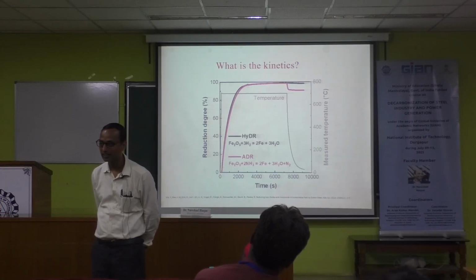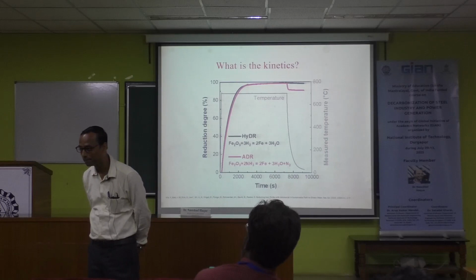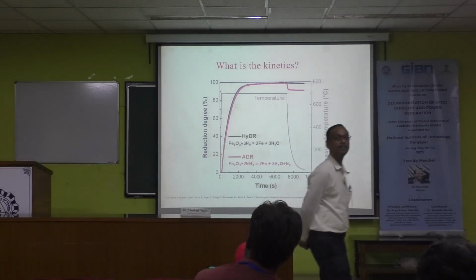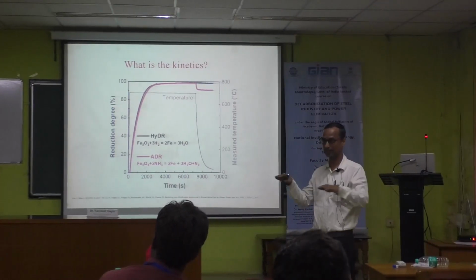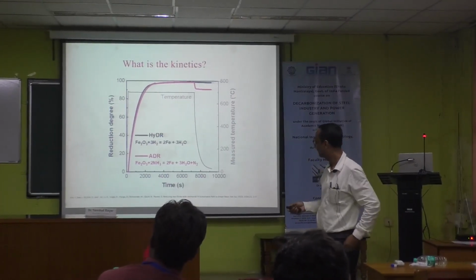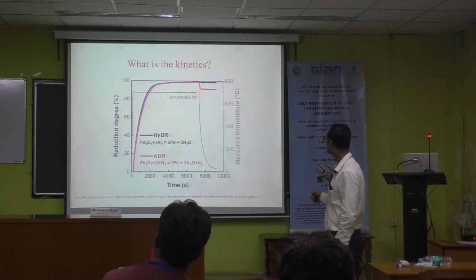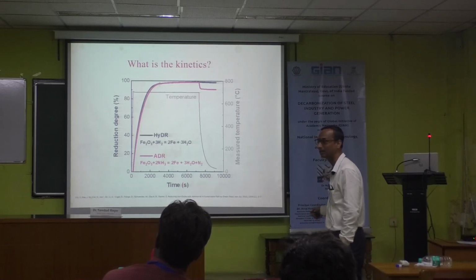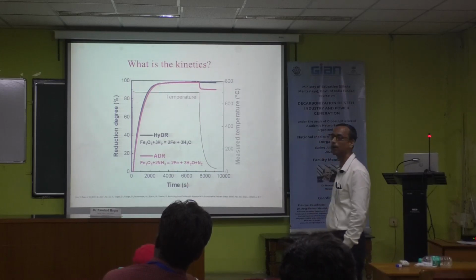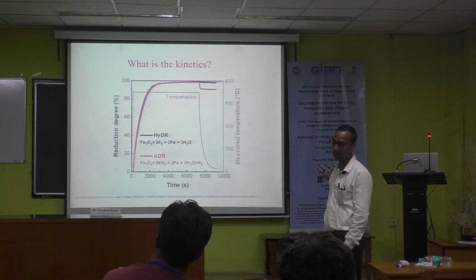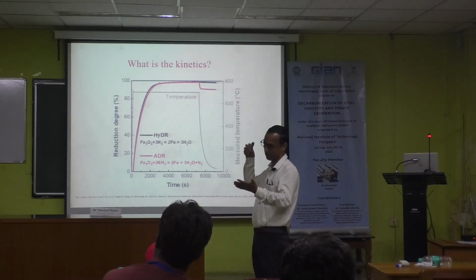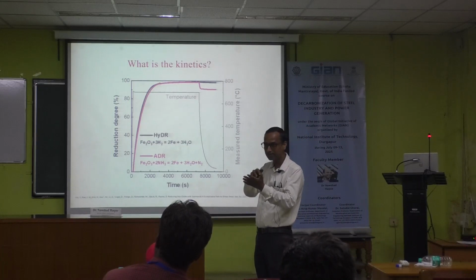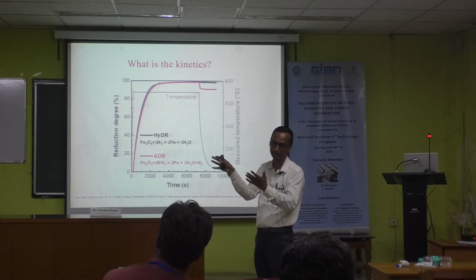Reversal, nitrogen entering into the iron. Yes, it is called nitriding. Nitriding is a surface hardening phenomenon. If you pull down the temperature, you can see the temperature graph is also there. When you decrease the temperature, only then is this weight gain seen. When ammonia goes over freshly reduced iron, which acts as a catalyst, it will dissociate to form nitrogen as well as hydrogen.